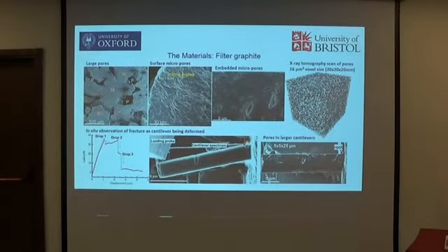I did microcantilever testing on the matrix of this material. So that's typical of the cantilever. You load it up and you see the load goes up nonlinear. Then the fracture is a progressive kind of fracture of ligaments.